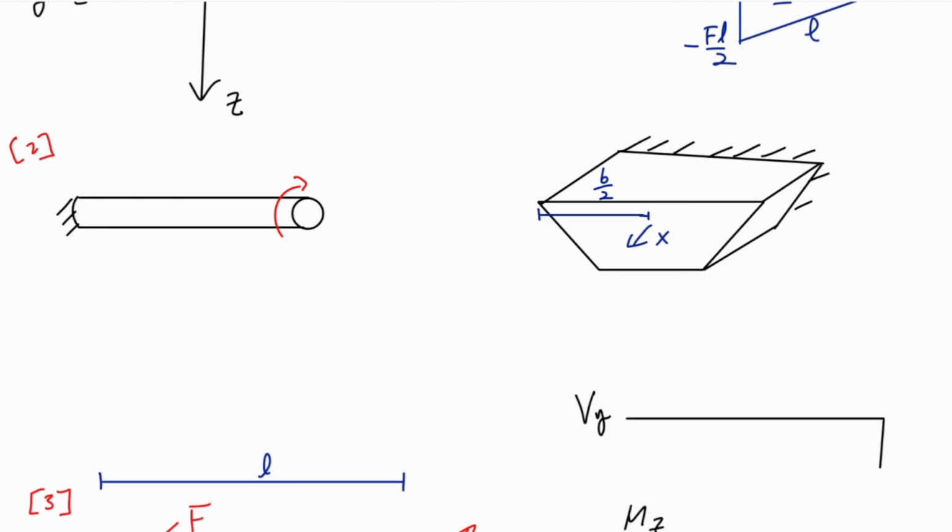A moment in the x direction is known as torsion. Torsion can only be caused by a moment in the y or z direction being transferred over to the x direction due to a change in geometry, or a direct torsional moment being applied to my bar. The torsion has absolutely nothing to do with the normal force, and please remember this. This is a very, very important point that some people get very confused about.